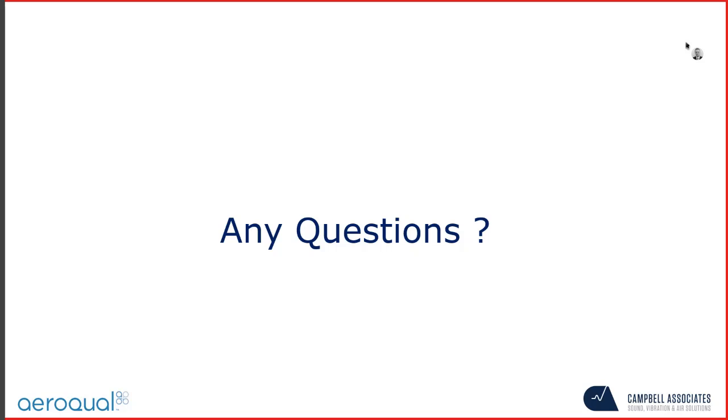Okay, another question here, Peter. How often do AQYs need to be co-located for calibration? Yeah, that's an interesting one. Certainly early on, we were talking about having co-location every 3 months. But I think we're now at the stage where we understand how they're operating so well that probably the only reason to take an AQY out of its installation is to change the sensors, which is normally every 1 to 2 years, and probably do the calibration at the same time.